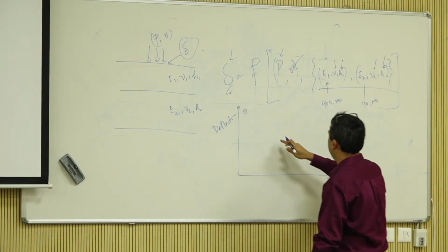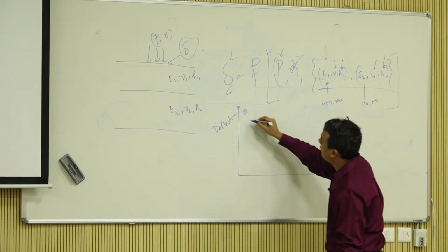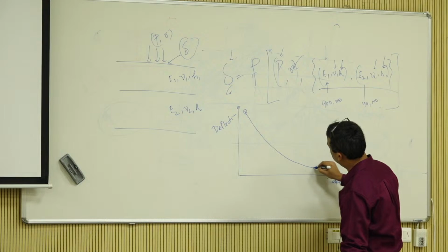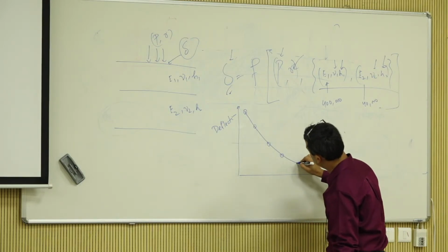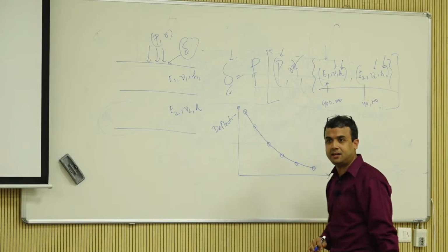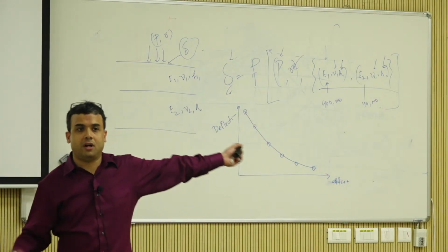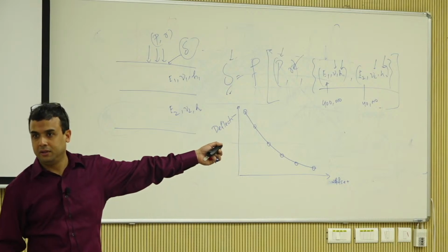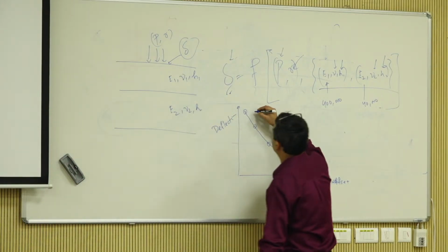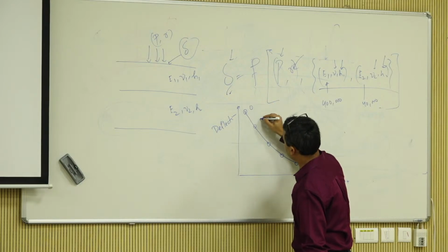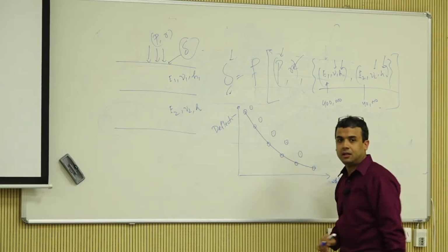As it goes away, away, away, deflection is going to go low, low, low, right? So this is my predicted basin when I used 400,000 and 40,000, right? But then you go and run an FWD and you find that the basin actually in the field looks like this.